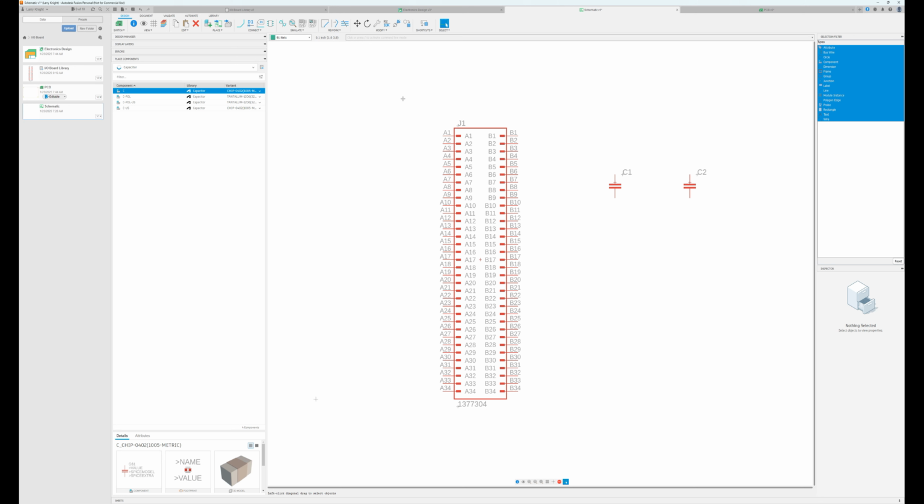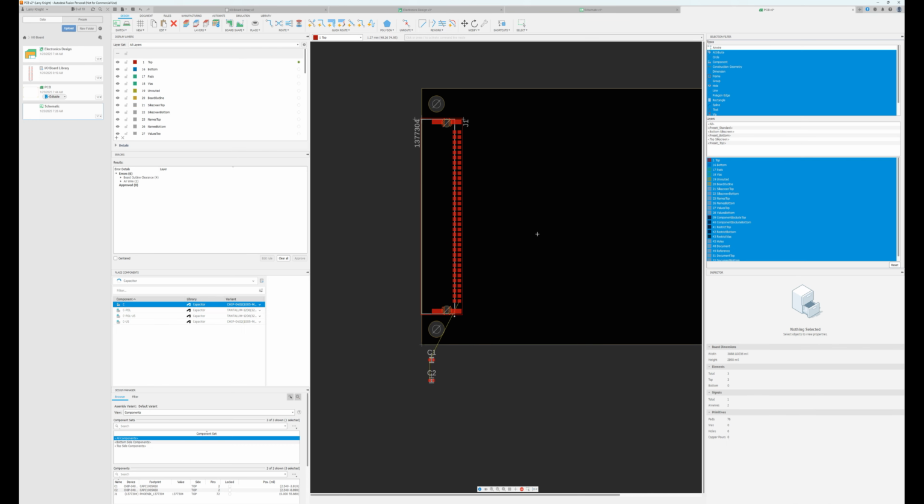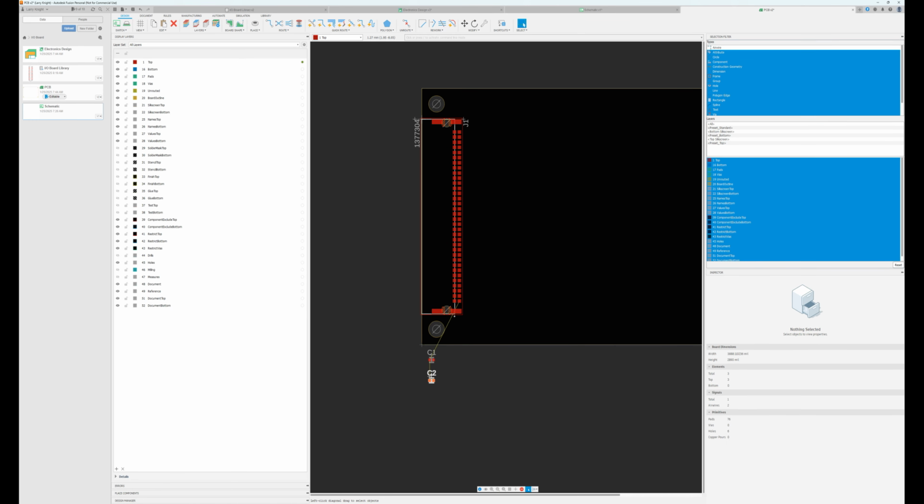Let's say, just for practice, we're going to connect a trace on here. So you come up here to connect, and you click on the net. Maybe from B1 you want to connect it here, and from here to here. All right. So then let's go look at what it did in the PCB. It places your components and they're connected by that trace.